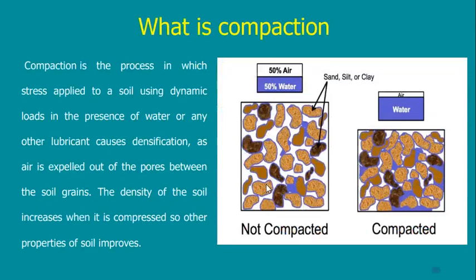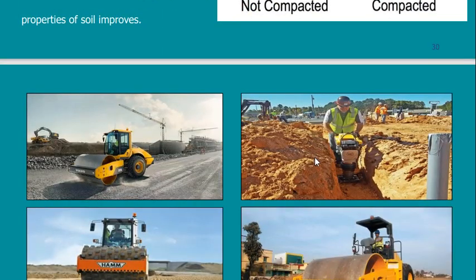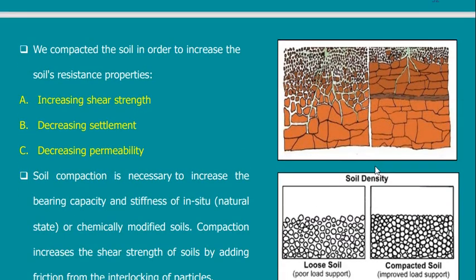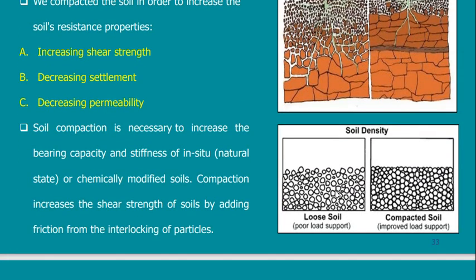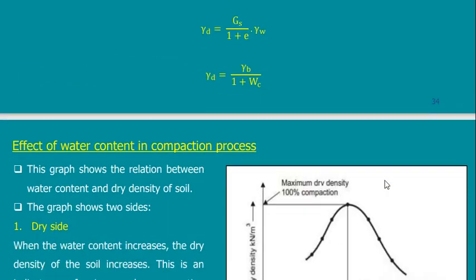So I go to the soil, try to push the sample together, the particles, compact them together, so that later when it is subjected to load, the particles are already settled and it cannot go further, or if it goes further, it will be a little amount. So compaction, this is the theory about compaction, is that you are just taking loose particles, put them together so that the voids are the minimum.